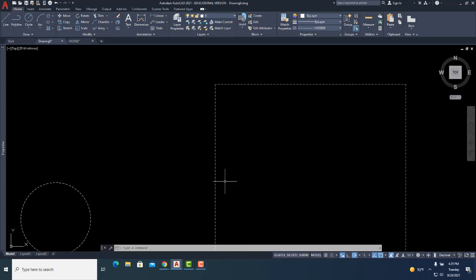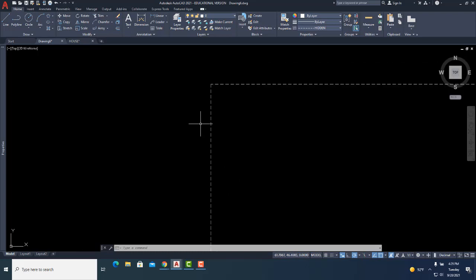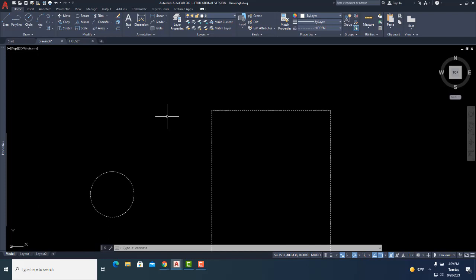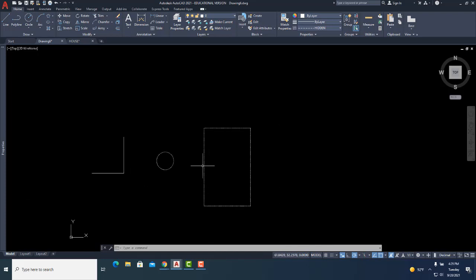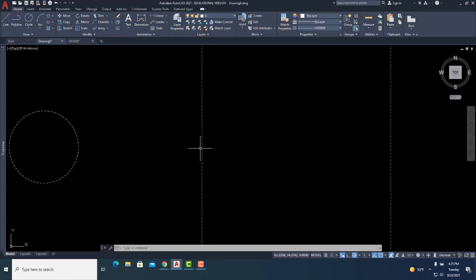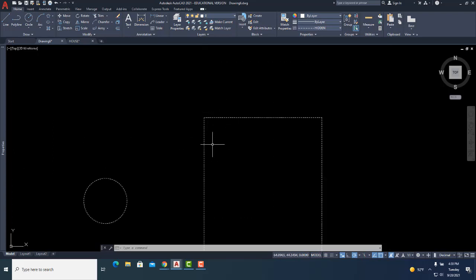Now, another thing that I want to show you briefly is the spacing, and I'm going to discuss this later on. There's something that's called line type scale, which means the scaling up or down of the line type. For now, we're going to leave it like this. I'm just telling you because it might be that it looks too small. There are different ways of making it appear the correct size in paperspace, and I'll go over that later on. So just FYI, there's line type and there's this line type scale, so two different things.